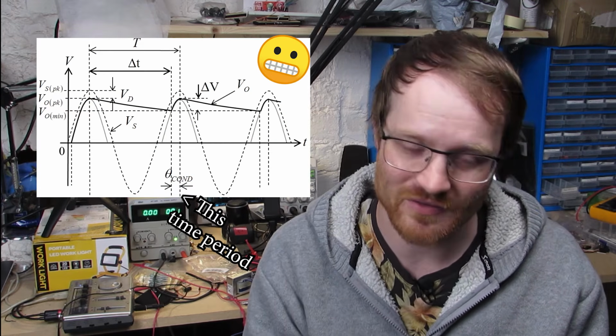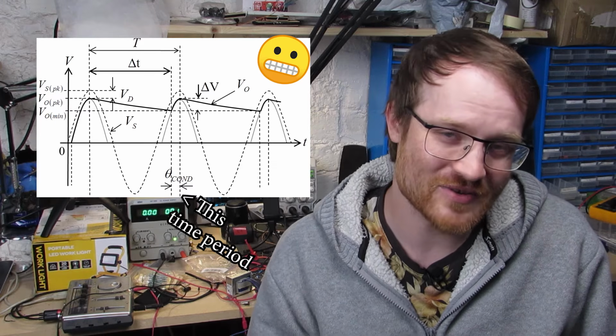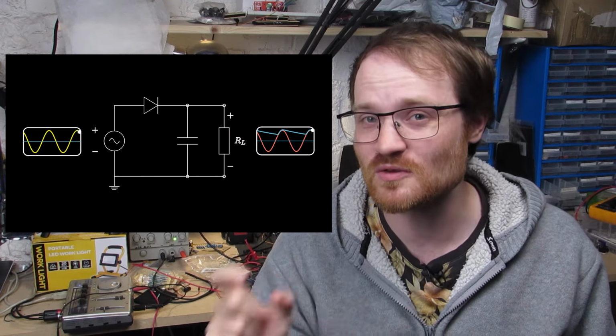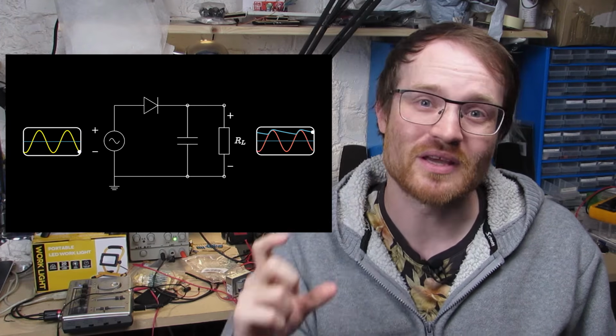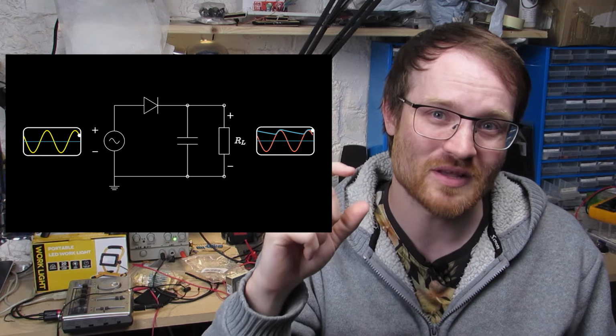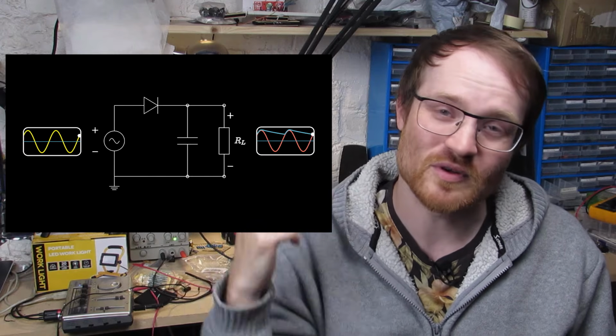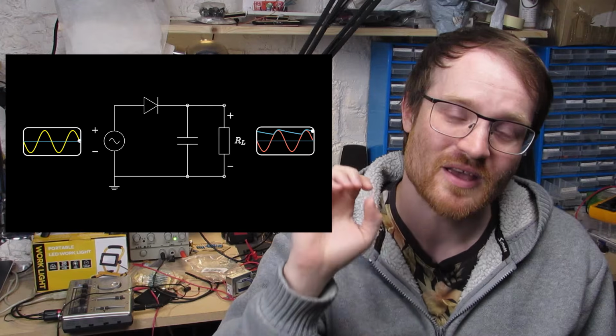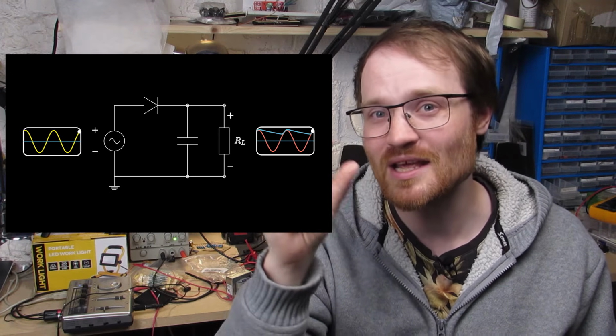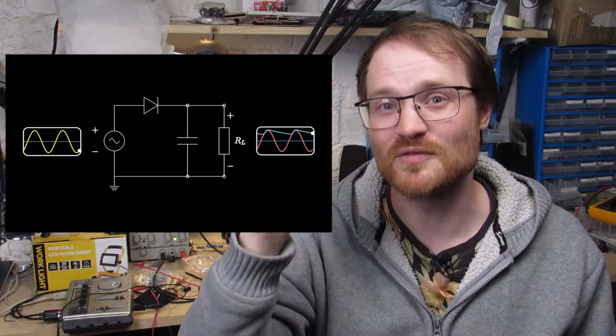Why we have to do that is because of this thing in rectifiers called the conduction angle of the rectifier. We have a catch-22 here where we need to reduce the ripple voltage, so we put large capacitors in there. But because we've reduced that ripple voltage with our large capacitors, and we're drawing lots of current, we need to shove all of that charge onto the capacitor only in the period above the ripple voltage.